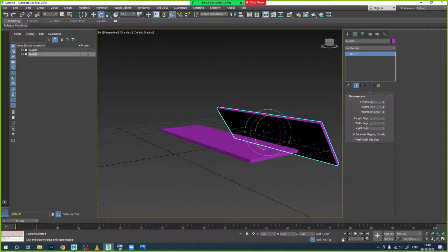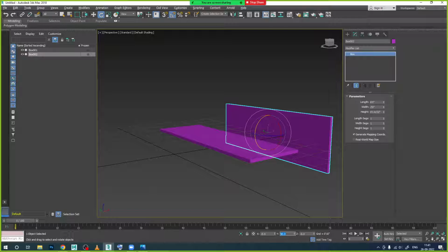Otherwise, for example, I have done this one, but I don't remember this option. What to do? As we have selected the rotation option, in the bottom you can see here, in this property, how much is it showing? 55 degrees. So select this one, make it 90 degrees and press enter. If you don't remember the first option, you can use this second option. Actually this is first, that is secondary. That is the advanced one, we can say, because you have an offset area also in that.